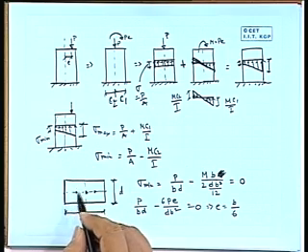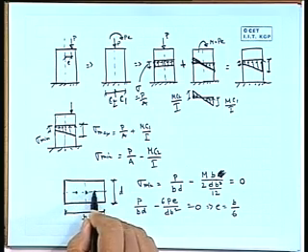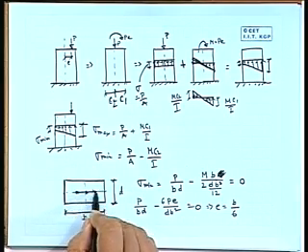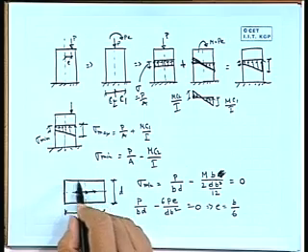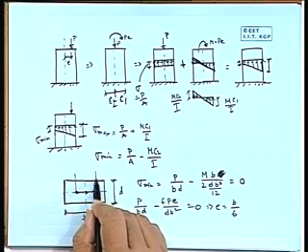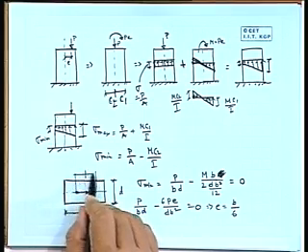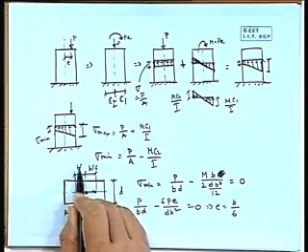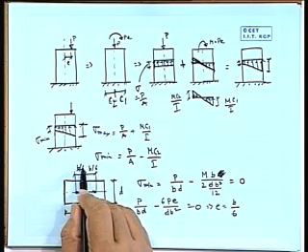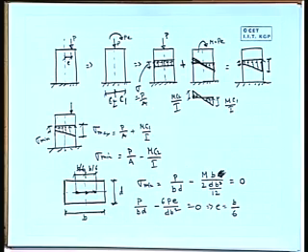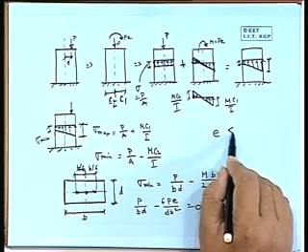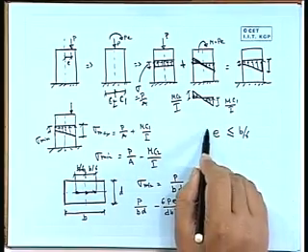So, this side it can be B by 6, and in a similar manner it can go here, right. So, that is the range. So, it can go up to here. So, you can say there should be a limit B by 6, right, or we can write E should be less than or equal to B by 6.